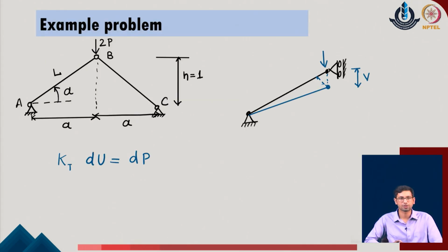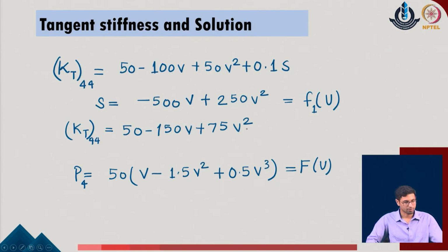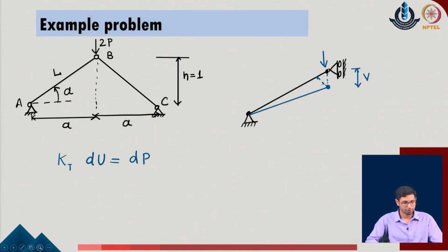So as we continue with the first problem which we have discussed earlier, we considered that there is a truss member on which there is a load which is active. We did the formulation of the given problem in which we reduced it into one element and considered that the single element can be used and we can apply the possibilities of the symmetry to get the response of the overall structure, because whatever the response we get for this half, the same will be the response for the other half of the system as well.